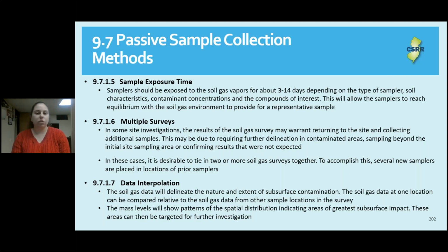I would also like to quickly again discuss some positives and negatives of using passive gas soil surveys. Positives include that these samplers can be used to help determine subsurface contamination over a large area. Installation generally requires minimal tool use, and a large number of samplers can be installed in a short amount of time. We found you can install about 30 samplers in a 2-hour time period. They do tend to be less invasive to properties, and so property owners find that beneficial.